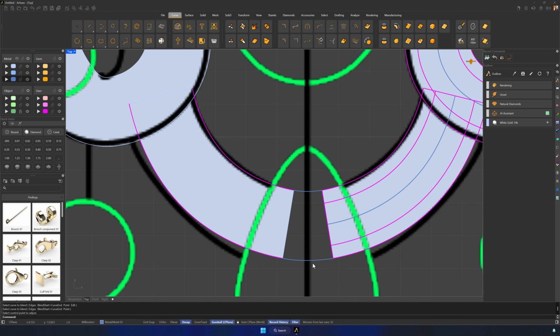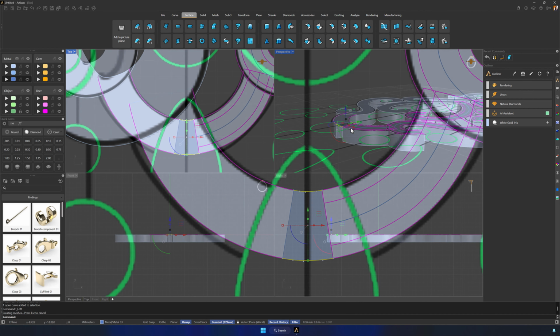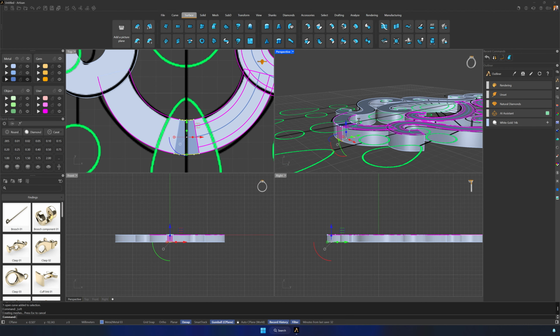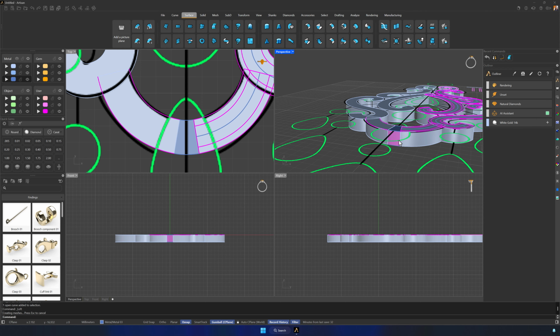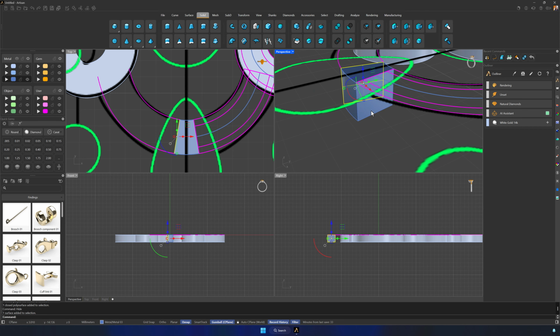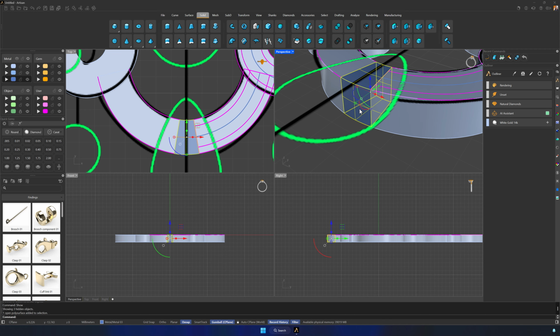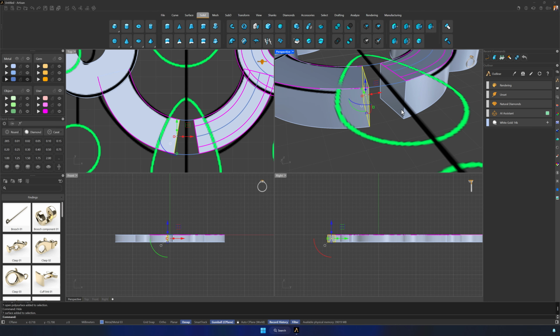Now I have both curves. With these, I go to Surface and create a loft, then extrude it by -1.8 millimeters to create the surface. If the extrusion appears inverted, type Flip in the command bar to orient it correctly. We can hide both halves, remove these two faces, then show everything again, and remove the overlapping faces so we can join cleanly. To select a face of a poly surface, we hold Ctrl plus Shift.